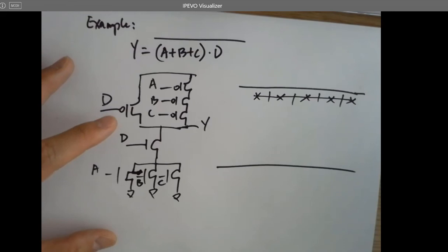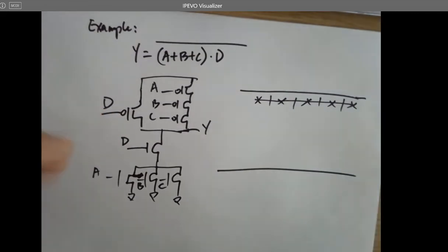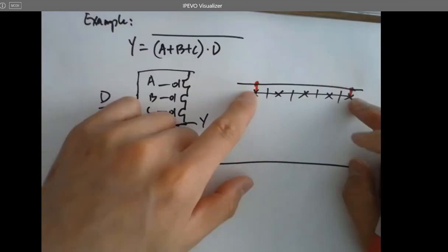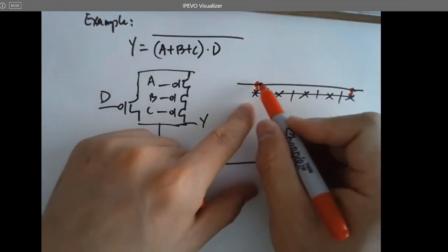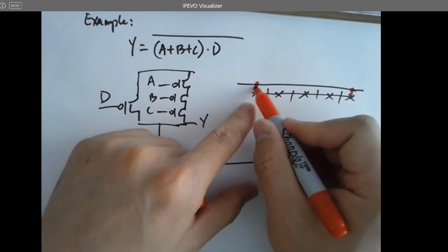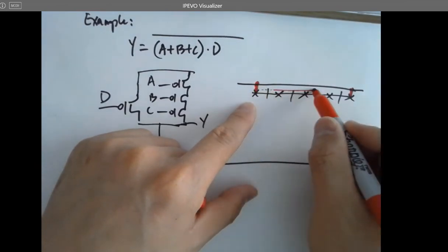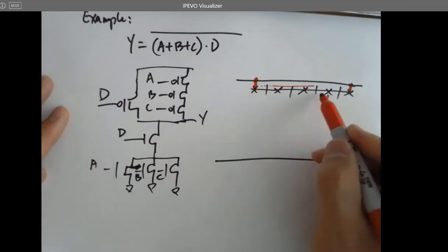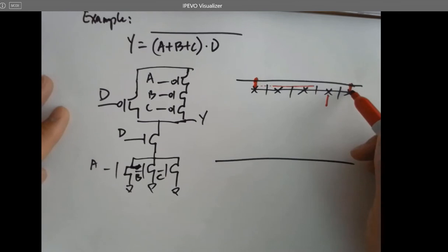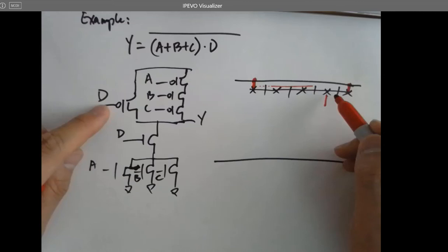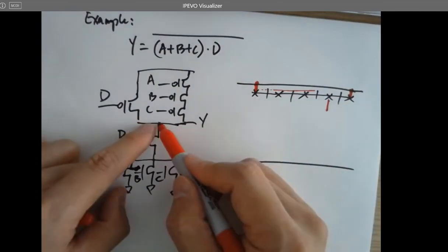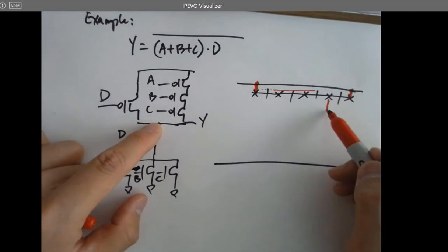It's not a unique way to do it, but what I'm going to do is introduce the VDD from the top to these two sides. So the signal comes to this P plus, it's going to flow through these 3 PMOSes and reach here. So these 3 PMOSes are in series, and VDD from here goes to this single PMOS, which is signal D. So that's the point where they get together. So that's the output.